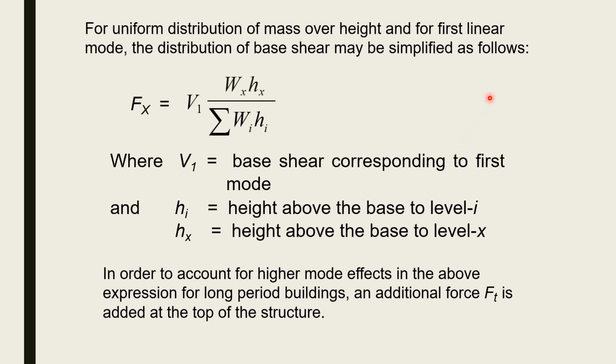In the free vibration analysis, I have discussed that when we push the mass horizontally, it will come back to its original position. After some time, it will stop. The first cycle of that building or mass or any structure is called the fundamental time period. And for the other higher modes, after some time the building will stop vibrating. This formula is for the first linear mode of fundamental period. To count the other modes, there is an additional force Ft added at the top of the structure.